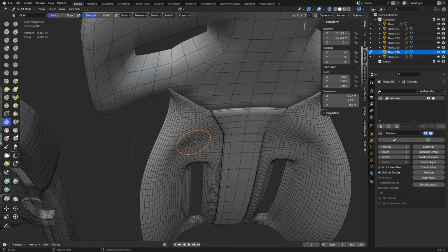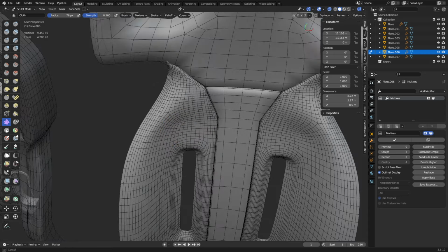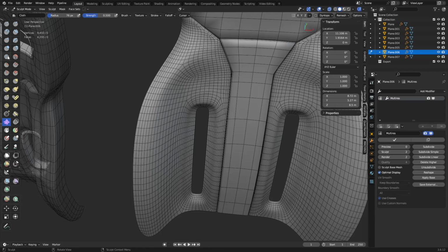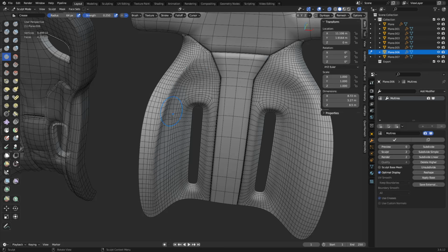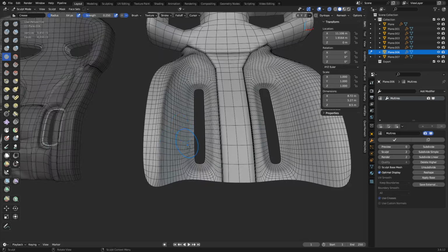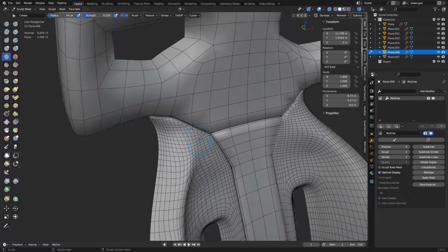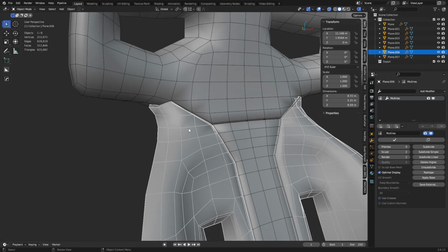Using the cloth sculpt tool, you can drag a little, add some roughness, right? We want to use creases, set pin pressure sensitivity, use a drawing graphics tablet, stylus. We can do creases, we can resharpen things. And we're not influencing the boundaries because the boundaries need to line up with each other, right? Otherwise, this whole thing breaks.